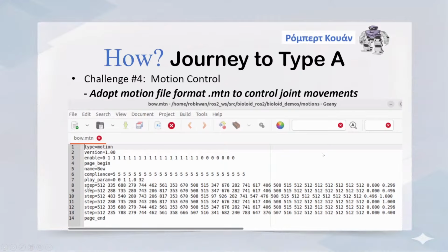The steps are the keys, with the goal position values they are trying to target. I had to interpret these carefully and correctly, because all these values are directly the values put into the motor registers, but in ROS2 I had to interpret them back to the correct radians or degrees to control correctly.